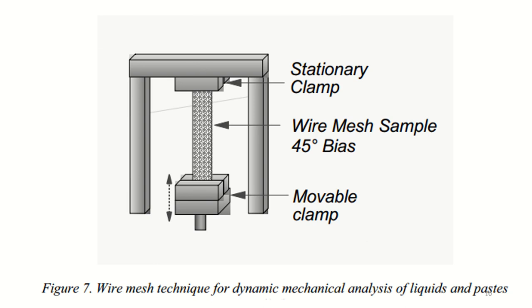Moreover, gelation is the first appearance of a cross-linked network. It is the irreversible transformation of a liquid to a gel or rubber that is accompanied by a small increase in the storage modulus.